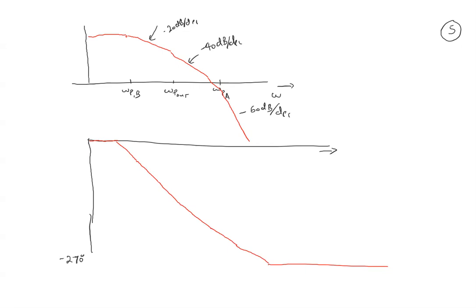Here at this point, minus 40. Then when they are reaching minus 90, minus 135 degrees, sorry, again, as I'm saying, might not be that much to scale, but that's what we need to do here. So the final angle is minus 270 degrees. And based on our relation, we know this system is not going to be stable. Why not stable? Phase is minus 270 degrees. Whenever the phase is minus 270 degrees, it is not going to be stable.